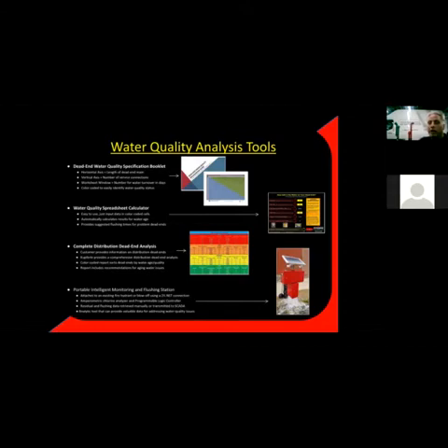This attaches to a fire hydrant, and this is a device that operates on a 24-volt lithium-ion battery with a solar recharger. And basically you have sensors and a PLC in this one. So you can actually put sensors in for chlorine. I can put sensors in for turbidity, pH, PSI, temperature, and so on. And what you do with this device is you tell the device, I want to maintain a parameter of water quality. So I want to flush, I want to make sure that my minimum residual on this line is a 1.5 and the desired level of a 2.0, and I want to sample the water twice a day.